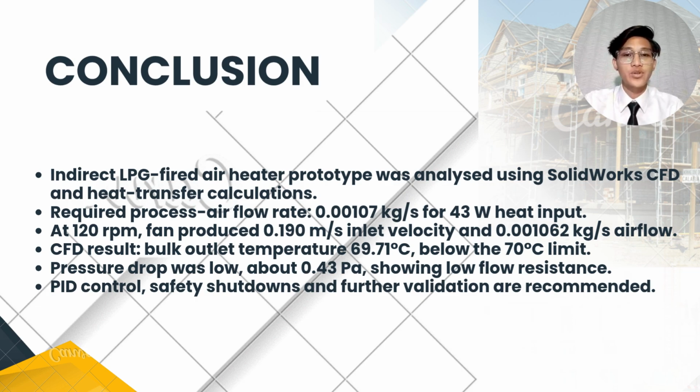The CFD result also shows that the bulk outlet temperature is 69.71 degrees Celsius, which is below the 70 degree Celsius limit. The pressure drop was also low at only about 0.43 pascals, showing low flow resistance. We also included PID control and safety shutdowns, and further validations are recommended.